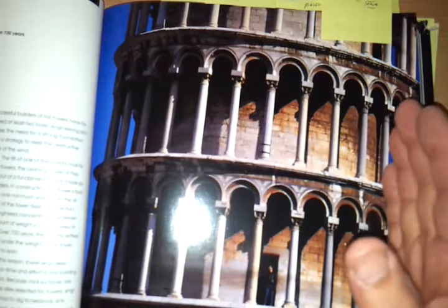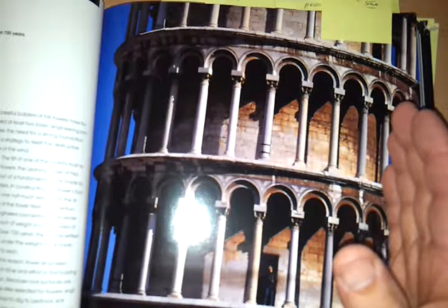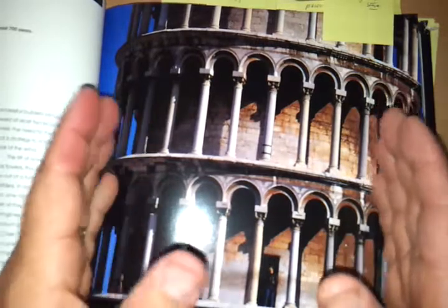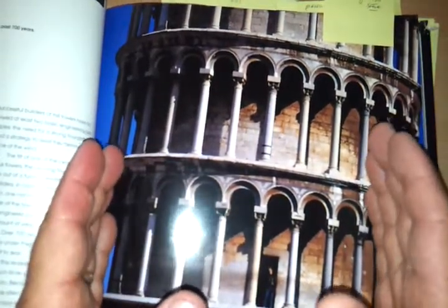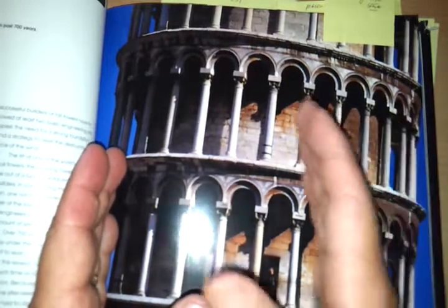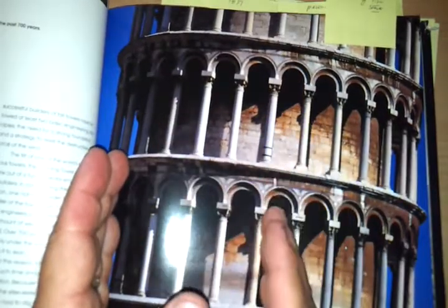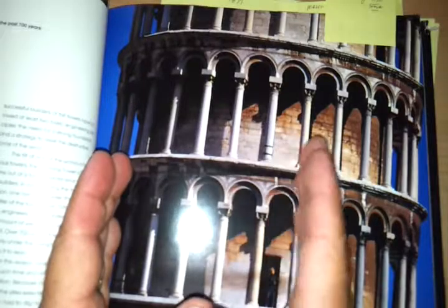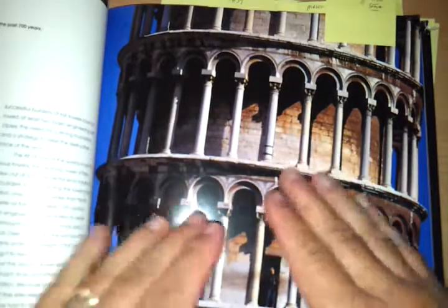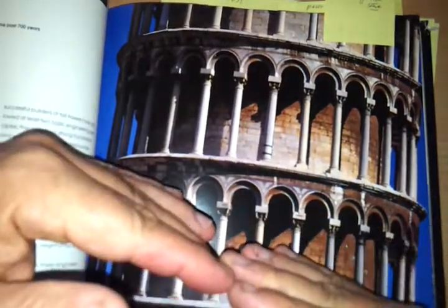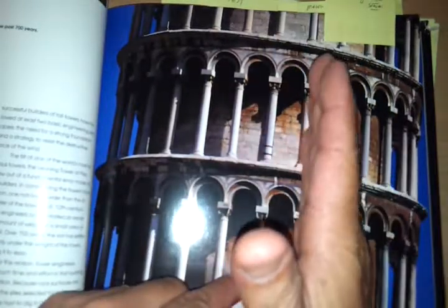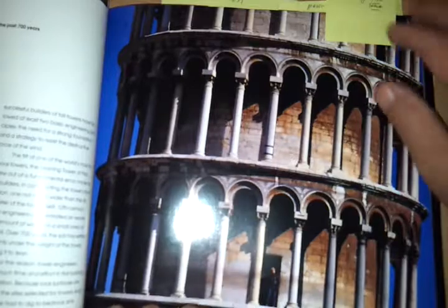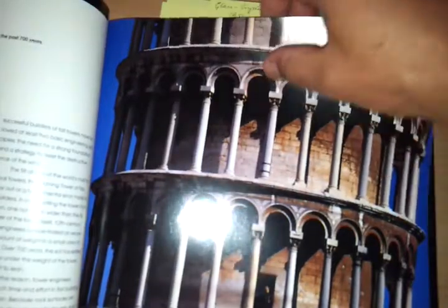Because stone is so heavy, so dense, in order to create a tower, a high structure, the stone has to be very carefully managed so that it's always in compression, and that the thrust line of force ends up in the middle, not to one side. And this is what's happening here. The foundations have been insecure, they've moved slightly, the thrust line of force is now moving towards the edge of the building, and the building begins to lean. So that's one of the big issues of dealing with stone.